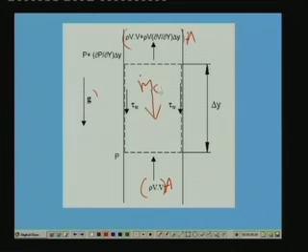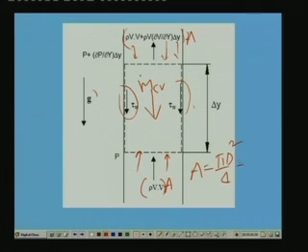Let us say this is due to the mass of the fluid in the control volume. This is one force, and you also have force due to shear stress at the wall of the capillary tube. This acts in the opposite direction, it tries to retard the flow of refrigerant, so this also acts in the downward direction. The pressure acts at the inlet of the control volume in this direction, and at the outlet the pressure acts in this direction. These are the different forces acting, along with the momentum in and out. Since the tube is cylindrical, the area is simply equal to pi d square by 4 or pi r square, where r is the inner radius of the capillary and d is the inner diameter of the capillary.